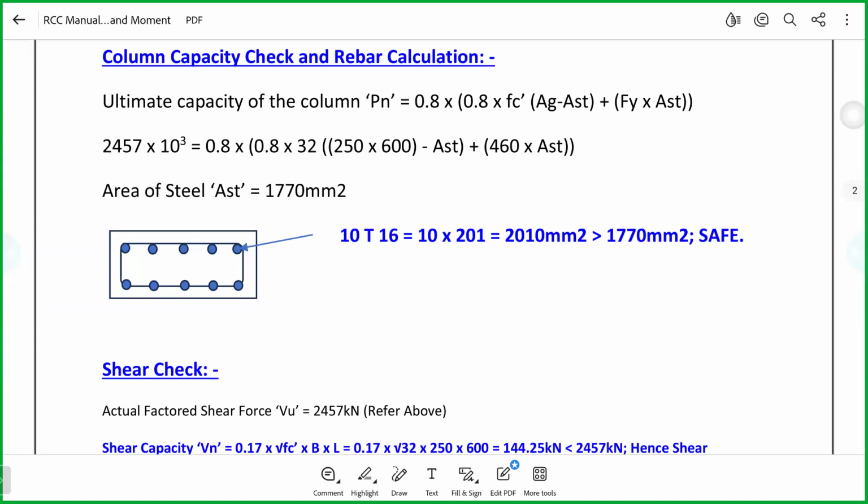Afterwards you have to find the Ast, area of steel reinforcement. Then find the shear, then check whether it's two-legged stirrups, and find the spacing. Then we have to show the drawings according to my teacher. So it's more detailed. But the only issue here is this is the Indian standard code, so this doesn't apply to me.